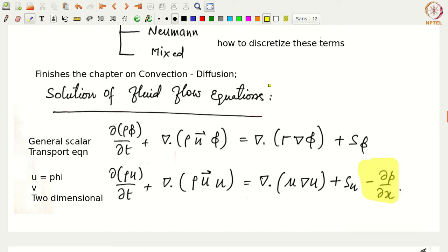Of course, we also realize that the term we have here is basically your Su. We have written it as source, but what does it contain? It contains not only the body force term, but also all the other miscellaneous derivatives that were coming out, which were not written here. It contains several velocity gradient terms as well.